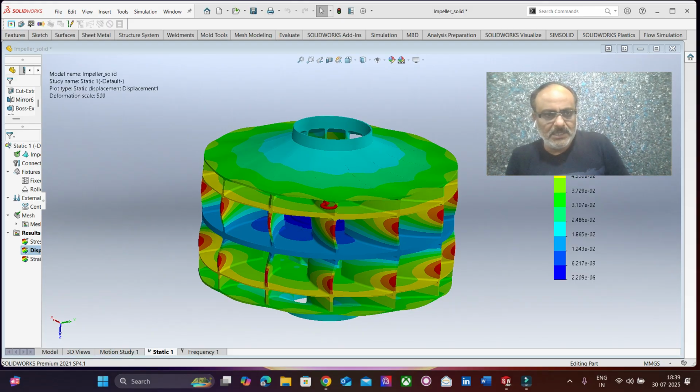The rolling loads, the braking loads, the traction loads, the shock loads, everything is properly transmitted to the ground, and then all these loads are distributed onto the pile. Now you want to check what the strength of the pile is, whether the pile is going to behave safely.